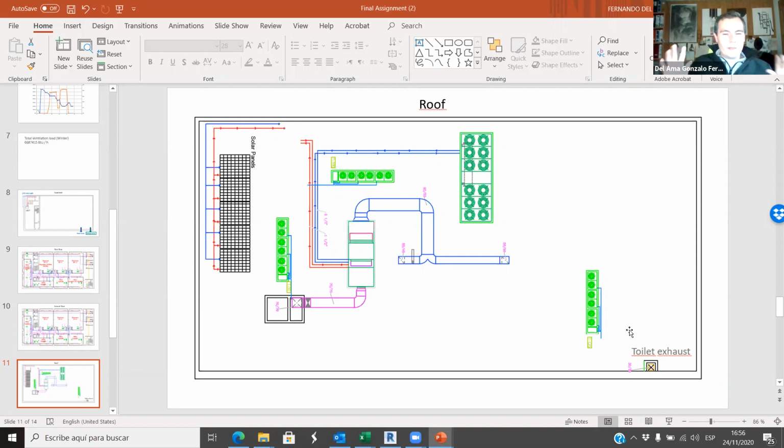If the system is smart enough, we can say, okay, now we have the perfect conditions to supply fresh air, but I don't want this chiller to work, and I want this heat pump to work, because these are the optimum conditions for this system. Now with other conditions, this is not the optimum condition for this heat pump, and the chiller is working better now. So I'm providing cool air with this chiller.